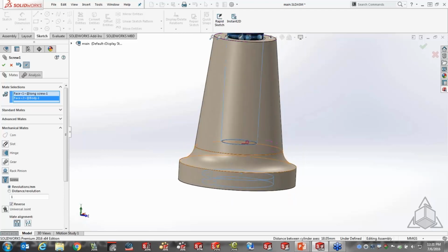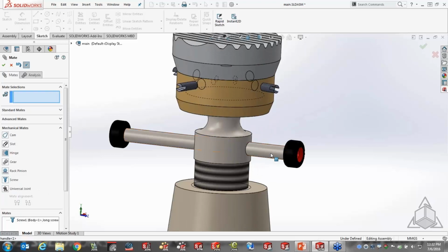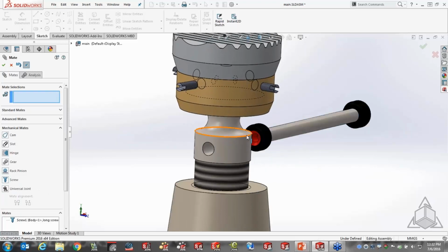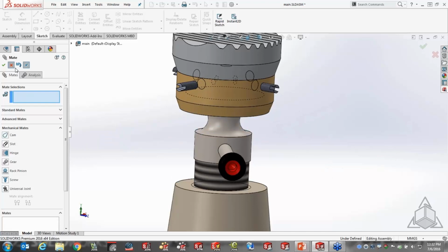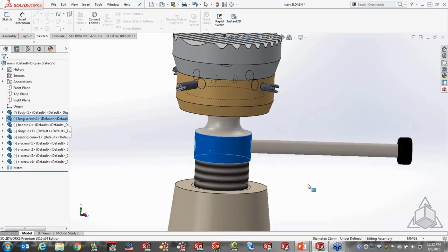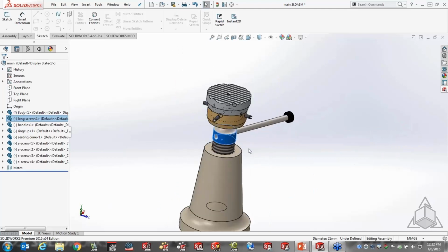And then the distance of them moving relative to each other using the axes based upon the number of revolutions. So instead of 1 millimeter, let's do, I don't know, 25. So as this thing works its way around, try to turn it through here, you can see that it will move up and down based upon the units. Hopefully that's coming across pretty good here.